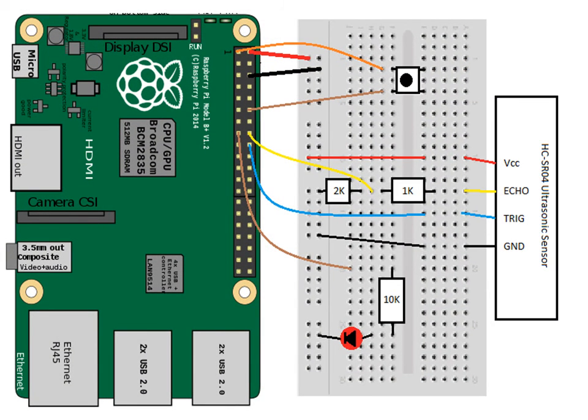The Logitech webcam is perhaps the easiest device to connect to our microcontroller. We can simply use one of the USB 2.0 docks to interface with the camera, and driver software is already found on the operating system. The connections involving the disarm button and alarm LED are very simple and straightforward. The button will be connected from a 3.3V pin to a GPIO input pin. The LED connection begins at a GPIO output pin connected to the LED and a resistor in series, and then back to the ground.